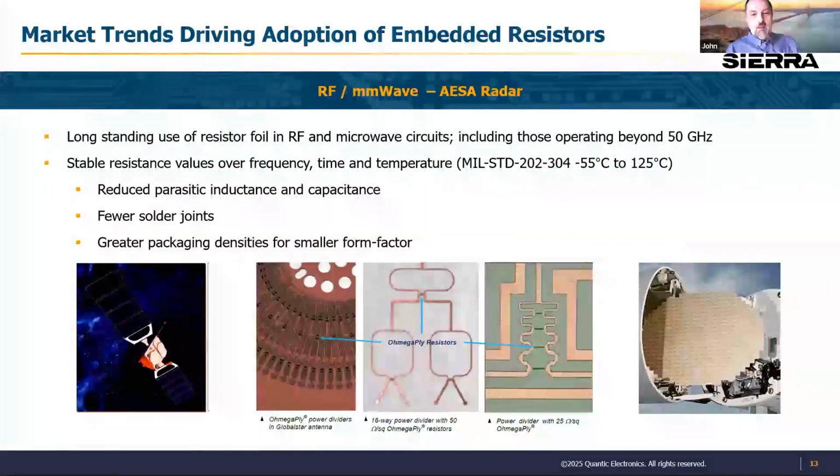Really driving a lot of the growth is the RF microwave world. Especially with 5G and other technology, people are going to phased array antennas, and basically these are the ones that use beam steering as opposed to actually having something rotate. They would have one that can do beam steering, and so they need a lot of things like Wilkinson power dividers and resistors.